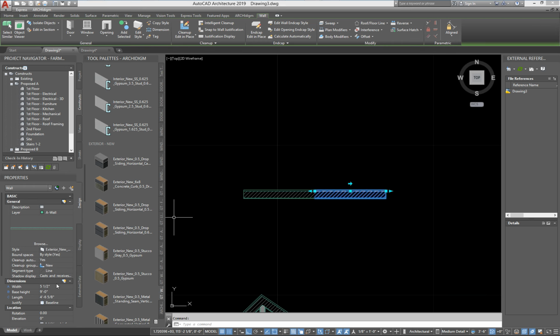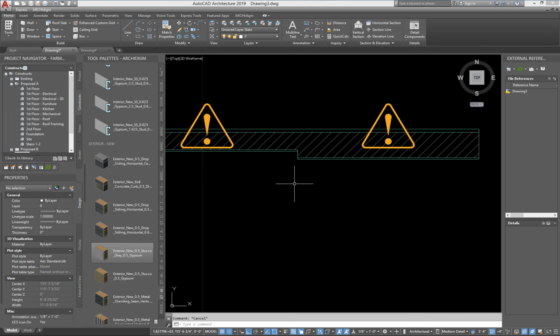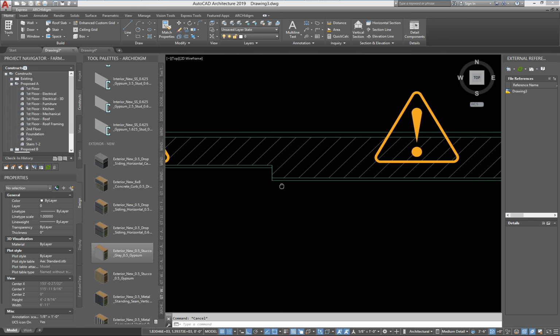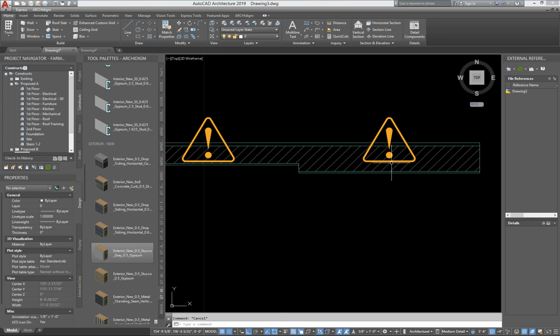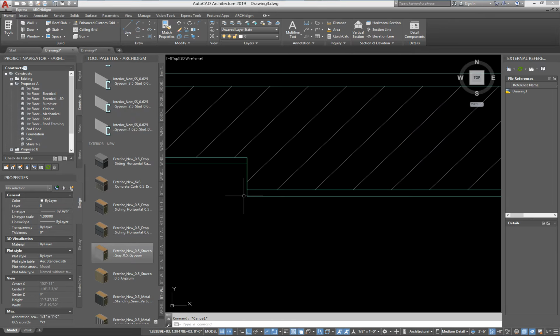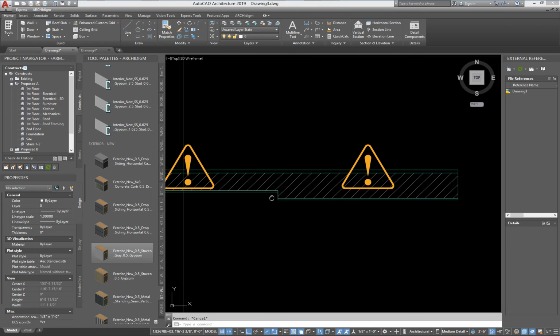What I'm going to do is run over here. I'm going to make that wall 8 inches wide. Okay, and I get this. If you've run into this problem, you probably know, oh man, this is a mess. Now, in fairness to the software, it's a little goofy, right? You've got your stud intersecting another stud, and what should occur here is some kind of solution to that, which would require some effort in doing a wall end cap style.